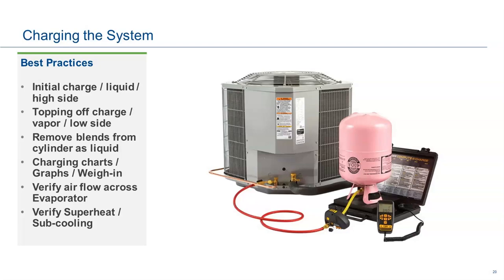And then last but not least, my favorite, verify airflow across the evaporator. Airflow, airflow, airflow. If you've ever been in one of my classes, you're probably giggling right now because I really hammer the airflow. If airflow's not right, nothing else will be, okay? So you have to have the airflow correctly, okay? And then it says verify superheat and subcooling. Let's talk about those two.